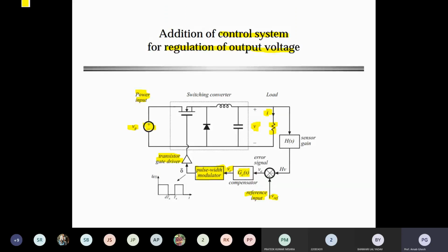Okay. So V0 max means your output voltage at maximum rated temperature. Sorry, V0 min means output voltage at minimum rated temperature. Then V0 norm means nominal output voltage, your reference voltage. T max means maximum rated temperature, T min means minimum rated temperature. So those are all the notations for the TC, the temperature coefficient.